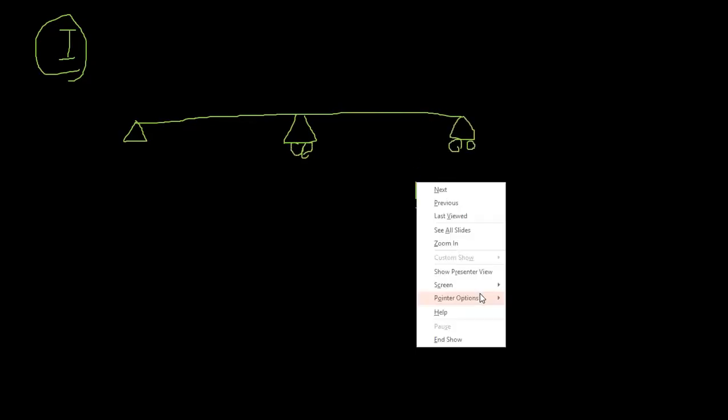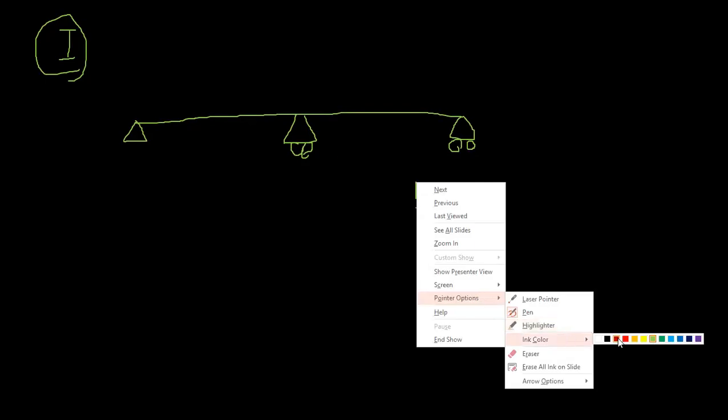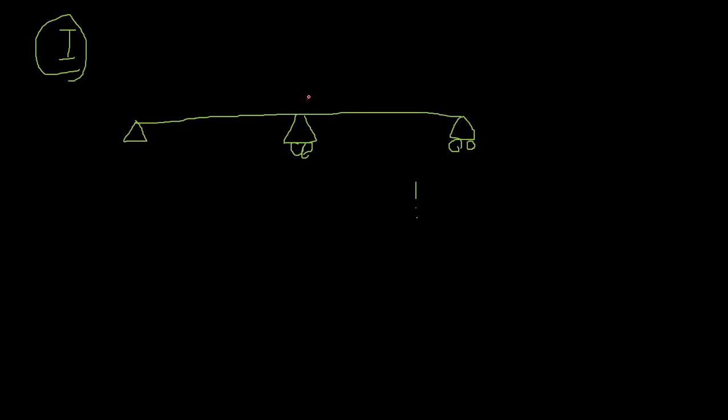Right? So if you apply the redundant, clockwise is positive, right? Because we are considering this part. So this is exactly opposite on the other. So here also clockwise positive. So if you apply unit moment, okay, unit moment, this would look like this.